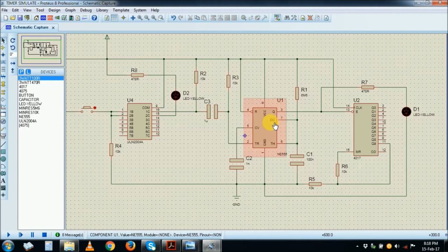So this is a monostable setup. What happens is, you have here a transistor driver, which, if you put in a high at the input, draws a low here, and the low is transferred to the timer, which is a trigger input. When the trigger input goes low, the output goes high for a given time, which is actually set by R1 and C1. Remember from our locking system, the electronic lock. If you have not watched that one, you can search for it and see how I've described it. So this output number 3 will go high for a given time, determined by these two components here. Normally this is the adjustable one that you adjust.